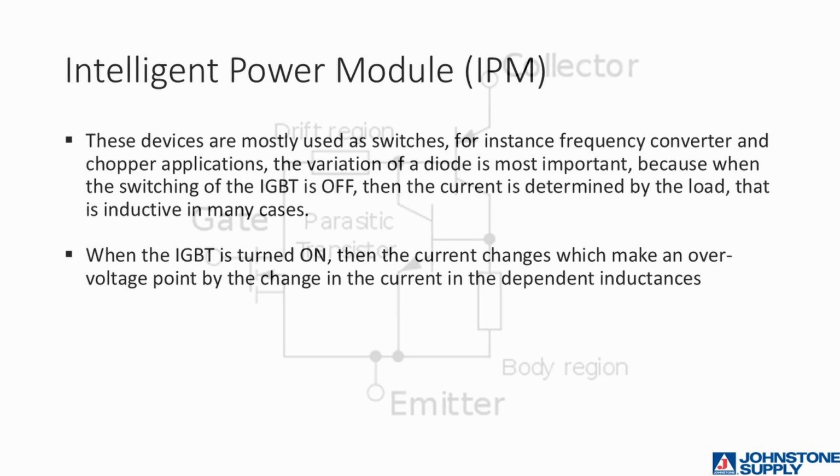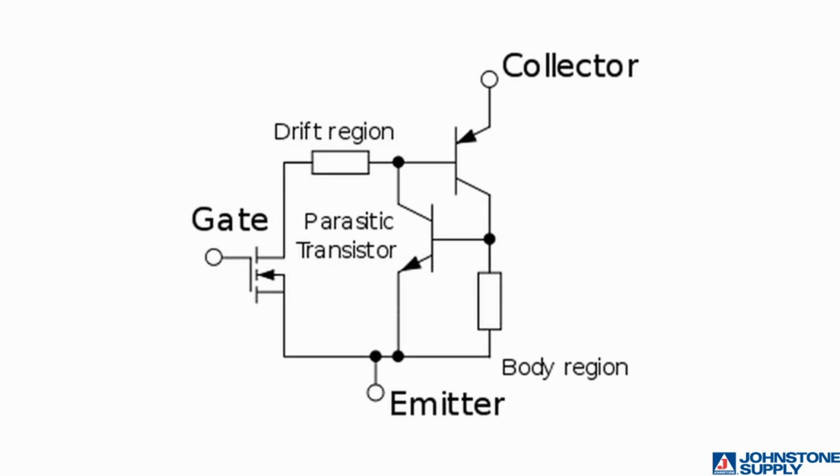The IGBT is a 3-terminal electronic component. The collector terminal is the incoming DC voltage. The emitter terminal is the exiting power going to the compressor. And the gate terminal is the trigger. The more voltage that is applied to the gate terminal, the more voltage is sent out to the compressor on the emitter terminal.